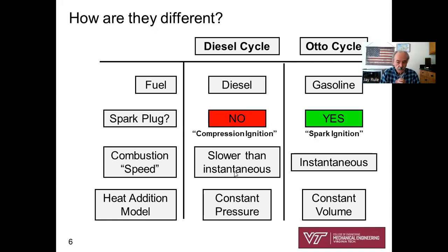And the way we're going to do that with our thermodynamic model is we're going to model the combustion heat addition process as a constant volume process for the Otto cycle model and a constant pressure process for the diesel cycle model.